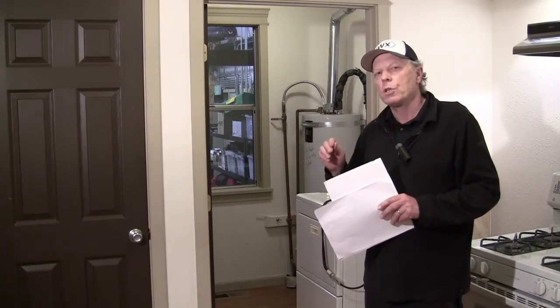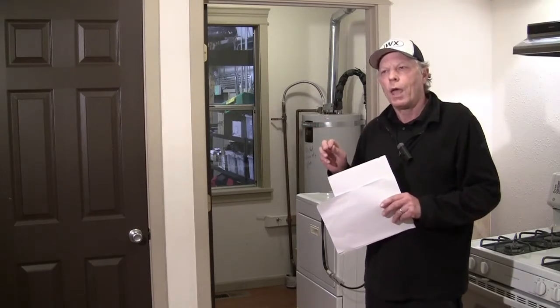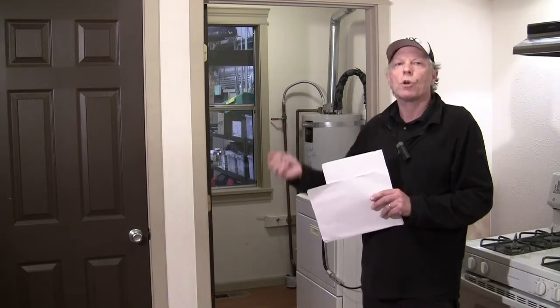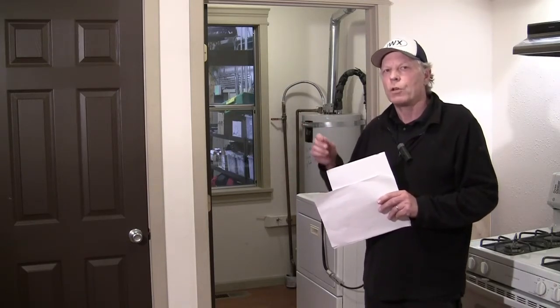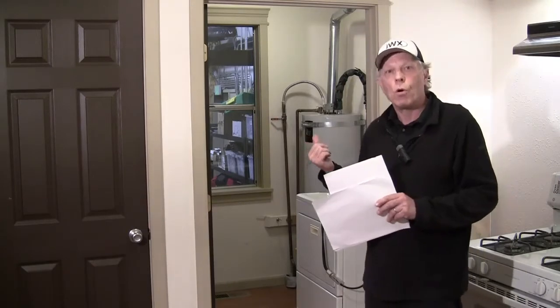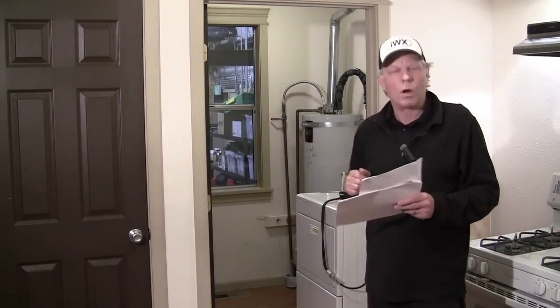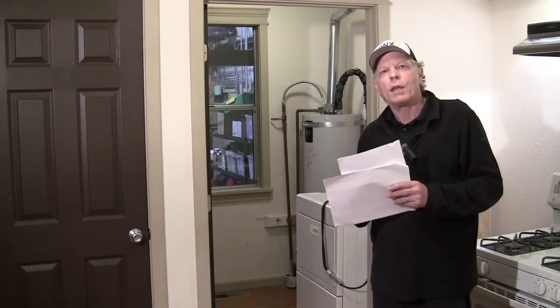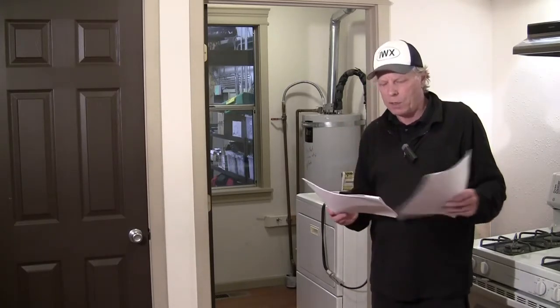And then we're going to position the interior doors. We always leave doors that have return airs or exhaust fans behind them open. But if there is not an exhaust fan or return, we'll leave that door closed to that room. Also, we're going to start with the combustion appliance room door closed, because that's what they want us to do off this sheet. That's where we'll start. And I'm going to go ahead and get that set up,